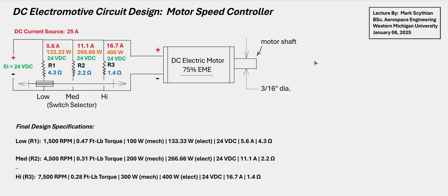So you divide the electrical output into that efficiency. You'll know the mechanical output at the motor as a registry, and then you can have another iteration typed in or programmed in the PLC that reverses it back to the actual electrical power. So you could have a good spreadsheet real time, either through Excel or Python or whatever, or C++, and this becomes a self-contained instrumented sensor.